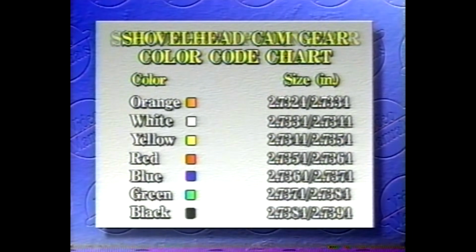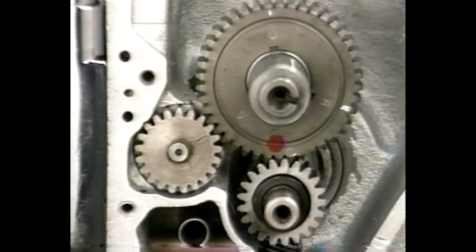This permits custom fitting of a drive gear with a pinion gear to give us the correct backlash of 0.002, allowing our camshaft to operate efficiently and quietly. First, we measure the pitch diameters of both our camshaft drive gear and pinion gear.